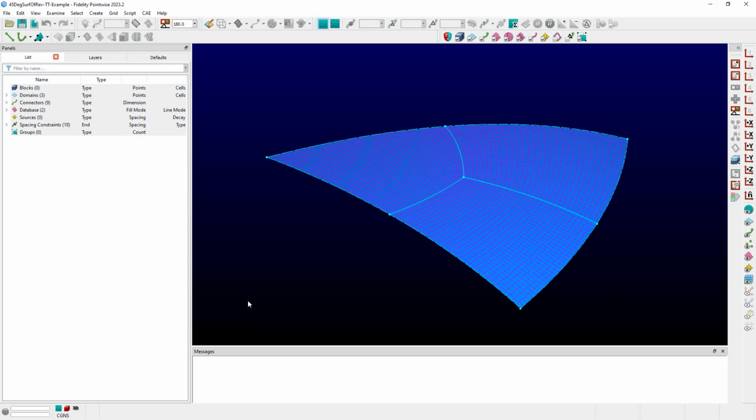Today I'd like to talk about an option that's available during curve creation and can be very useful when creating topologies, specifically connectors, that begin on your geometry or surfaces in your geometry and span away from that geometry. And in those cases, often you want that topology to be normal to the geometry.